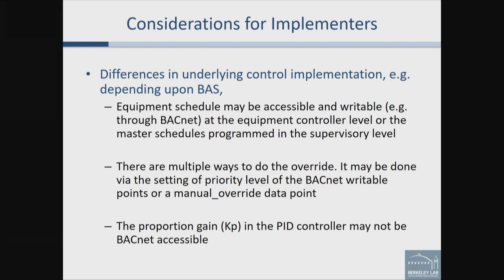We also need to figure out whether the things we want to override are BACnet accessible, because some of these parameters are usually not exposed to third parties for access.